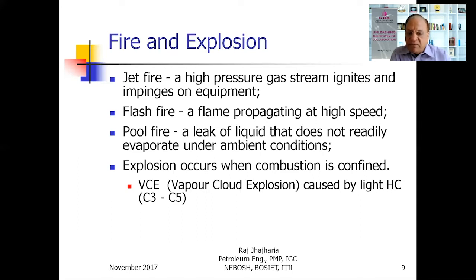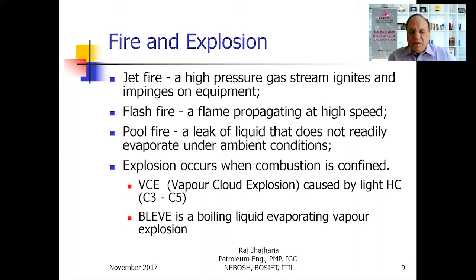Suppose there is a storage tank which leaks, and this liquid, which is in the liquid form inside the tank, when it leaks, it will immediately get converted into vapor, and that will form a cloud. And this cloud can move with the wind, and wherever there is a source of ignition, it will catch. And the moment it catches, it will explode like a bomb. And that can cause huge damage. That's called vapor cloud explosion.